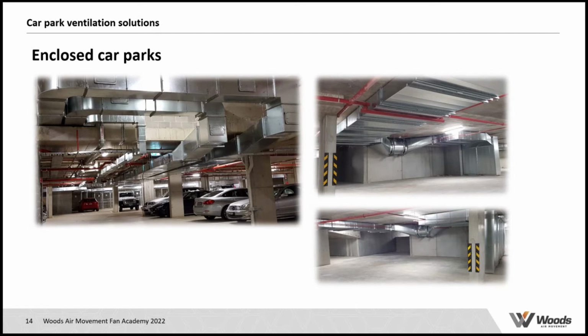Now, for the fan engineers listening in, if you look at the upper right image, you'll see an actual flow fan with two rather awkward transition pieces. Obviously, you can get almost anything to work, but from those transition pieces, you can already see that this is not going to be a very efficient design from an energy perspective. So you would require quite a lot of power on the fan motors to push that air through the ductwork to overcome the duct resistance.